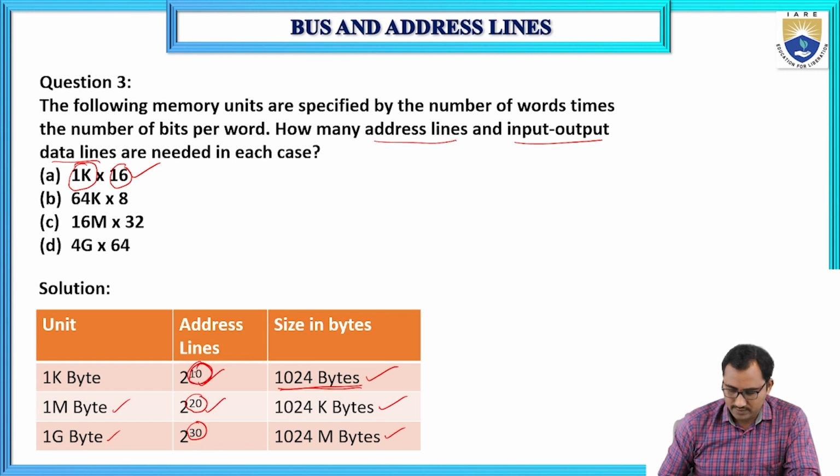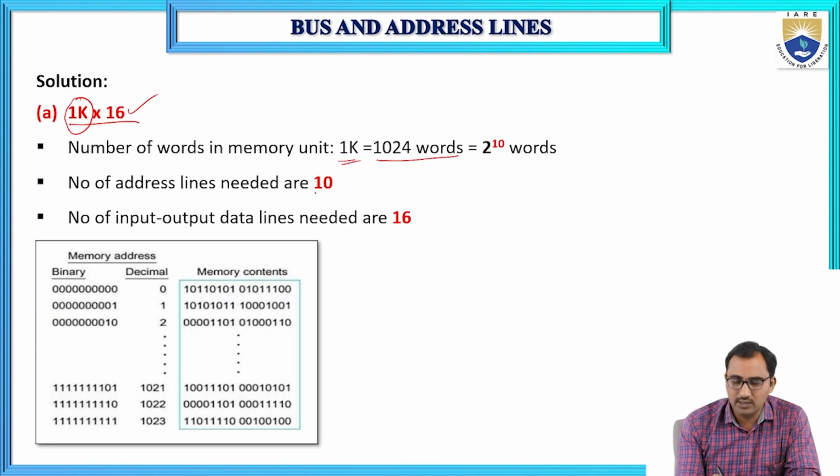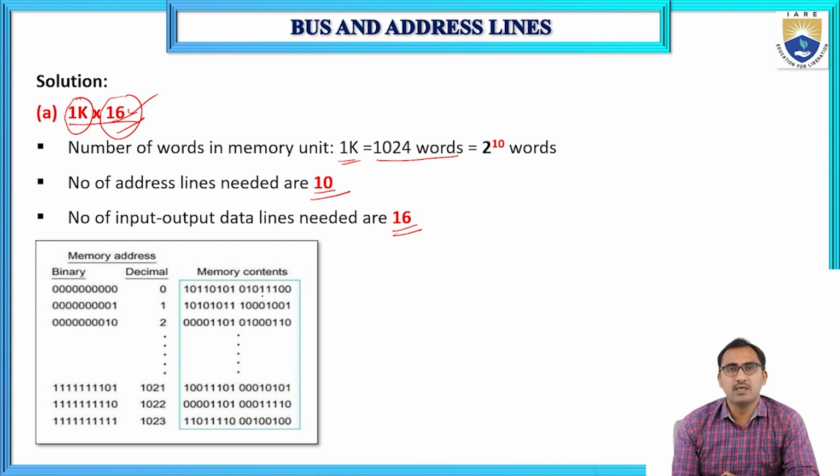And the number of input or data lines needed is 16. So here you can see how the memory looks like with 10 address lines and 16 data lines.